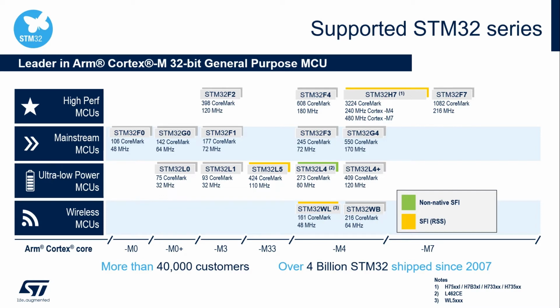Instead of being an extension of the system bootloader in ROM code, in this case, a custom implementation of a secure bootloader offering the RSS services is provisioning the user flash of the micro. Additional details will be provided in a section dedicated to the STM32 implementation, together with some pointers to the documentation, where you can find all the information for each family.